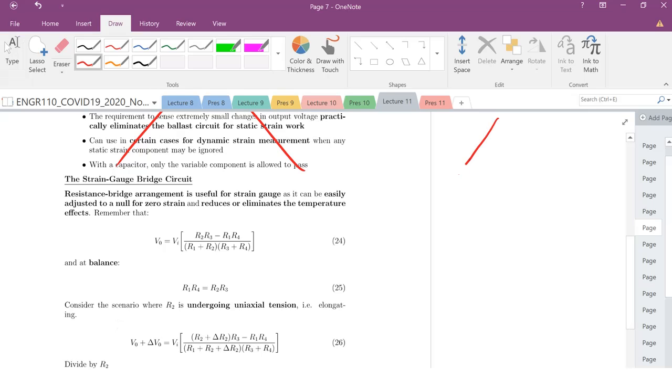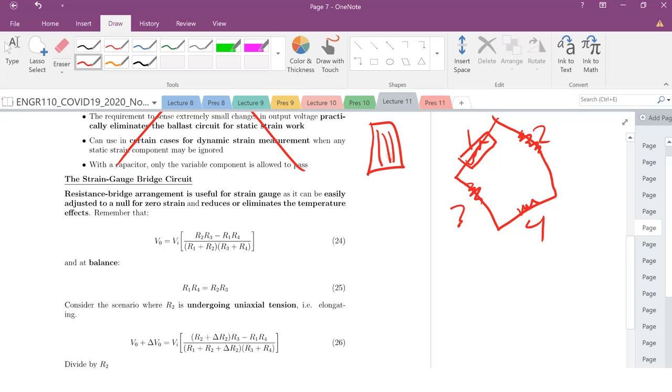So we've set up this idea of the standard configuration of our Wheatstone bridge. Standard configuration is very important. So 1, 2, 3, 4. That is going to be the standard configuration that we will set up quite often, or actually all the time, for our Wheatstone bridge calculations. So 1, 2, 3, 4. These can be either resistors, or, as we'll see in a second, we will sometimes replace these with strain gauges, where our strain gauge will always have these wires, wire bonded, again, resistive strain gauges along the long axis of your rectangle. So strain gauge bridge circuit.